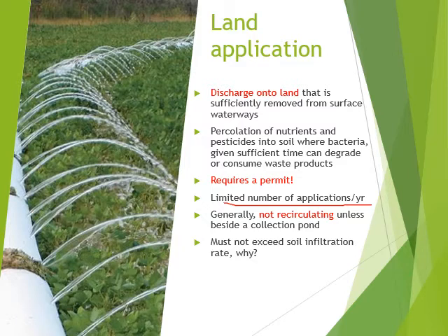Obviously the main thing is you cannot exceed the soil infiltration rate. If you are discharging on the field and it's not percolating into the soil fast enough, it will actually run off the side of the field and it could go into a ditch or a wetland. So part of the application process means that your soil has to be suitable. The Ministry of the Environment comes out and checks all these things. It's a big deal. They don't want you doing this regularly, right? But in an emergency situation, it can be done.